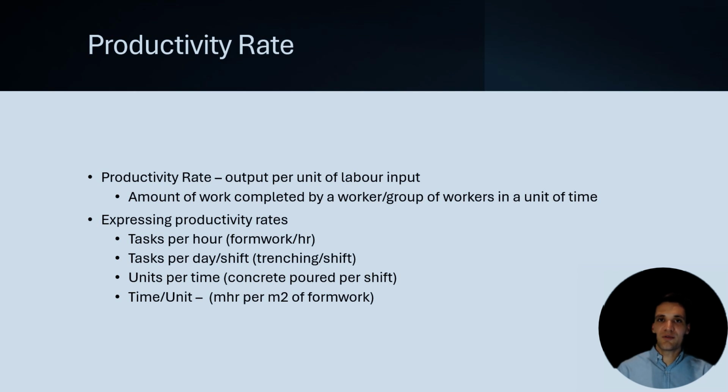That we always have to be careful with, because when people express a shift rate, they're factoring in non-productive time. So they might say a crew can do 2,000 meters per day. That doesn't mean 10 productive hours per day. If you have 1.5 hours a day of non-productive time, that means they'll do 2,000 meters in 8.5 productive hours. So when we're talking about shift rates, you just have to be really careful that when people are expressing shift rates, they're already including non-productive time.